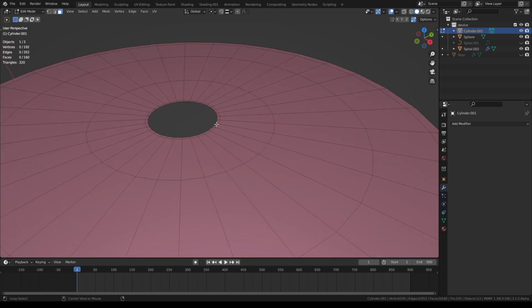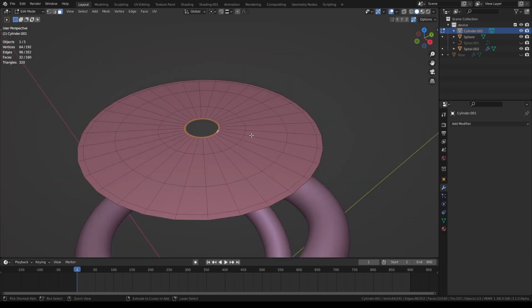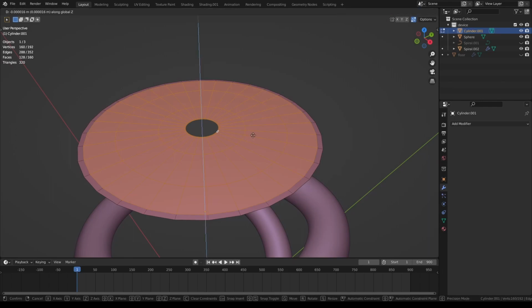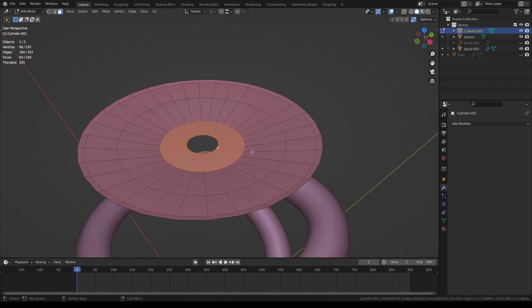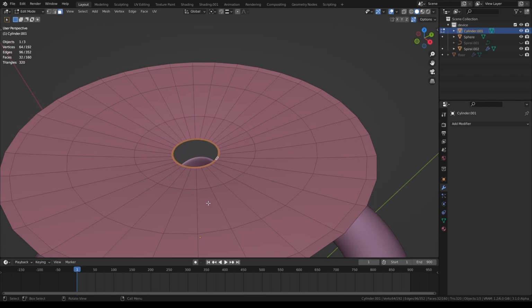Now Alt-left click on the inner faces loop, to select it. Using Ctrl+Numpad Plus you can select the next loops, select all the faces before the last loop. Move them down on the Z-axis, with Ctrl+Numpad Minus deselect the last loop, and move them a little lower to create an incline, repeat until the last one.